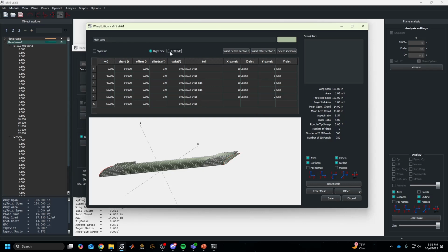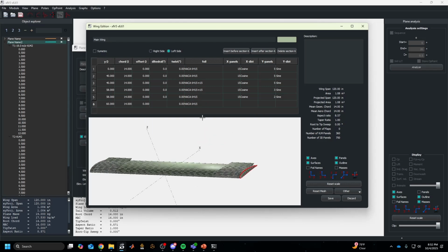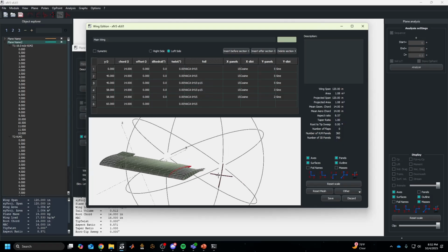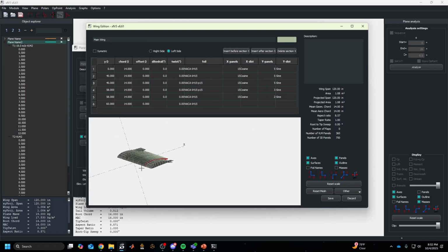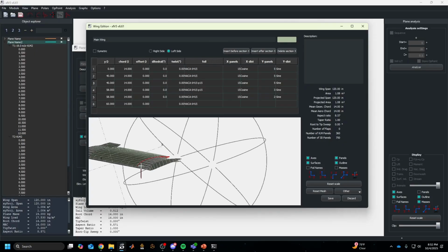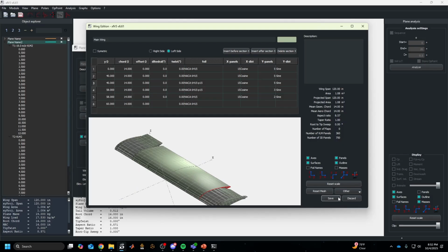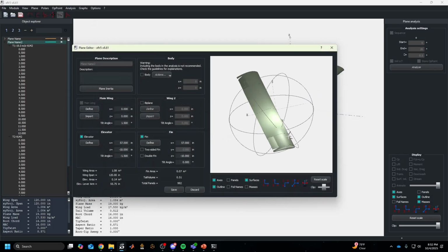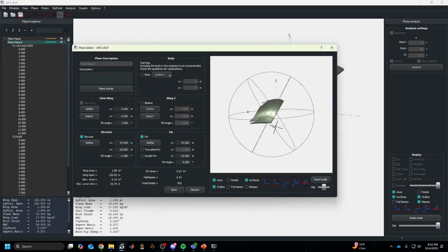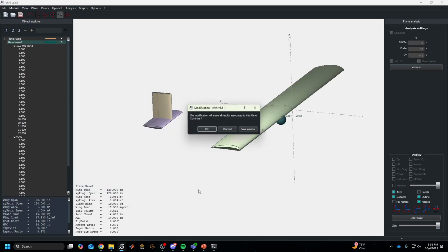So you could use this to define the left side to have that positive 15. Okay, so we're gonna do that, right? Because this is how ailerons work. If you're rolling the plane, you don't want this to be symmetric. That would just give you a flap basically, to give you pitch, right? So there you go. This is kind of cool. I've never done this before actually, but now you can see our aileron deflection. So you would want to do this with the elevator in a similar fashion.